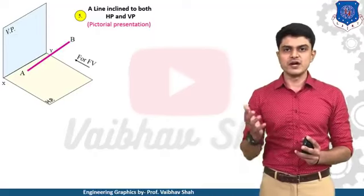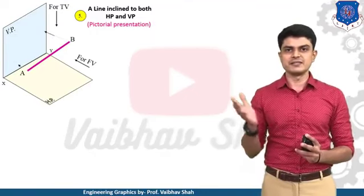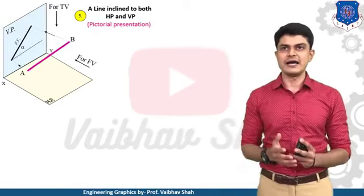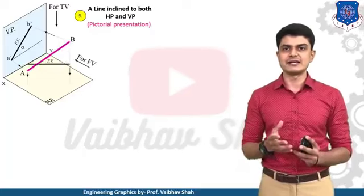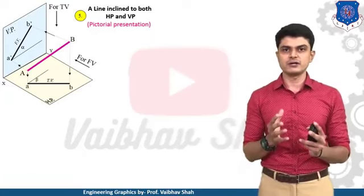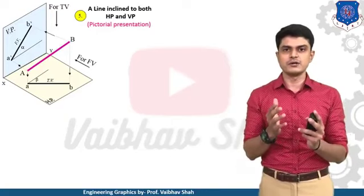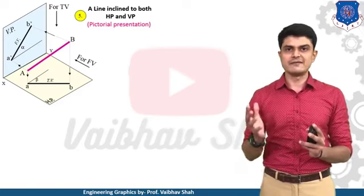So now let us take the front view from this direction, and the top view from this direction. When we take the front view, we have one line inclined to HP by angle theta, or you can say angle alpha. And when we take the top view, we have one line inclined to the vertical plane by angle beta. The projection on the vertical plane is your front view, denoted by A dash B dash. The projection on the horizontal plane is your top view, AB. So we have these views.